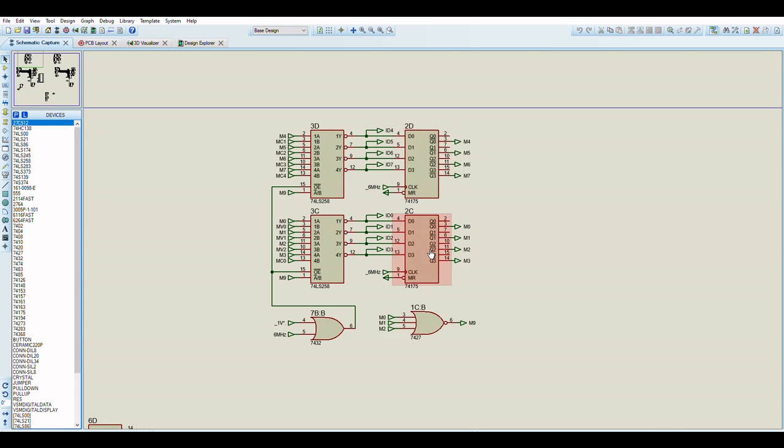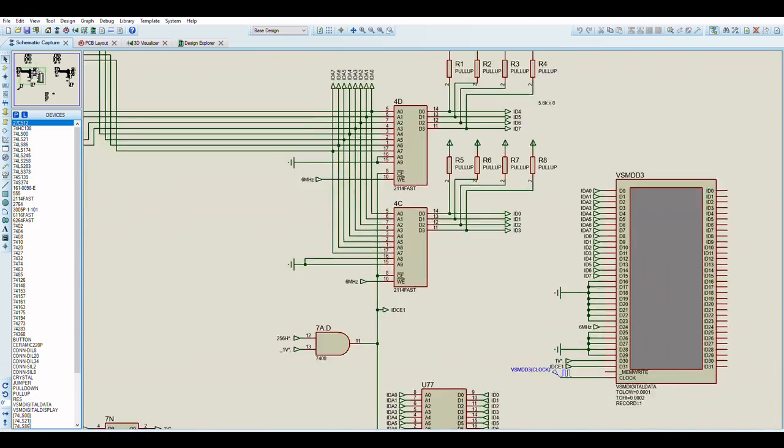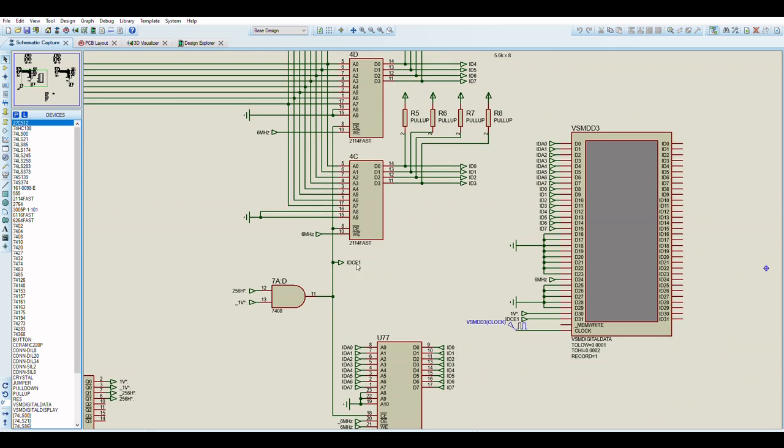So what it does mean is that these RAMs will be very sensitive to timing variation. I noticed this when I was trying to convert the board to be double horizontal resolution, or even just 50% more horizontal pixel resolution. The timing was extremely tight. So what I'm thinking is that if I really want to produce a better version of this hardware at some particular point with more horizontal pixel resolution,